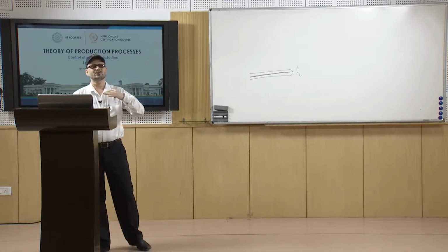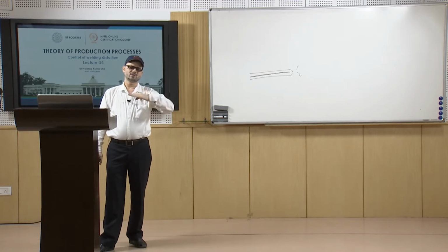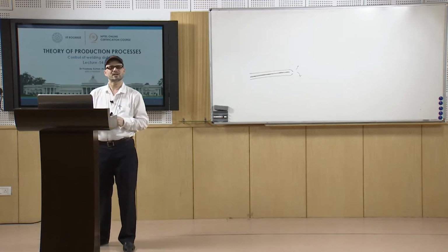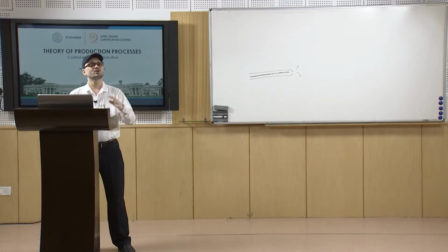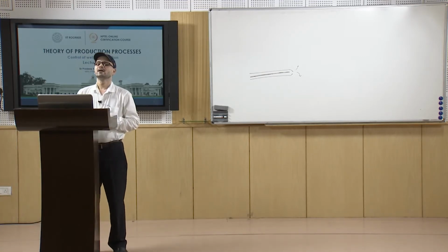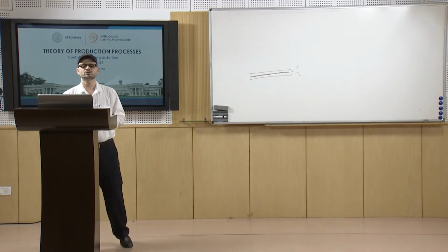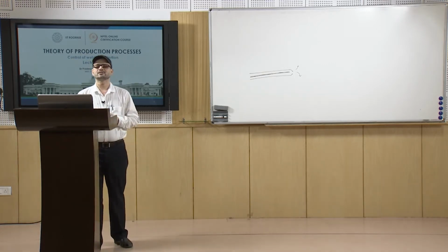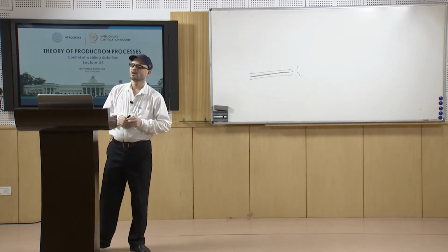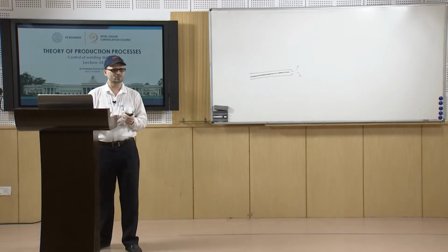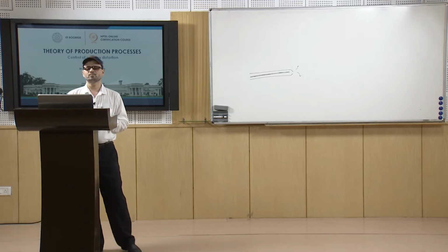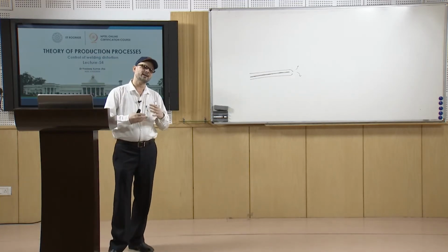So, you try to follow the welding in the direction in which you have maximum degree of freedom. That way, that is the better practice of controlling the distortion. Then you have least weld metal deposited. Basically we know that as the quantity of weld metal deposit becomes more and more, the amount of contraction will be more. So, that will lead to more of the distortion. So, you should see that you are not putting any excess metal.